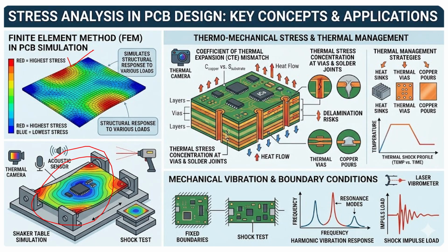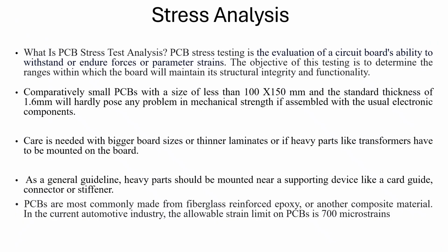Your PCB should not break, right? So how much stress can it suffer? Mechanical vibration and boundary conditions, and how much shock it can sustain, these other things are important here. Not only mechanical vibration, but also thermal management, how much temperature variation your PCB can sustain. These are the things that are important while we are designing the PCB.